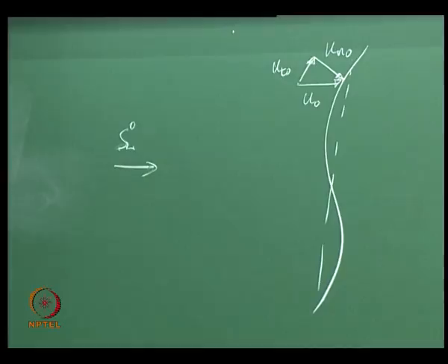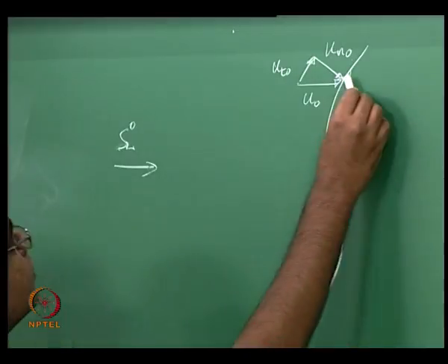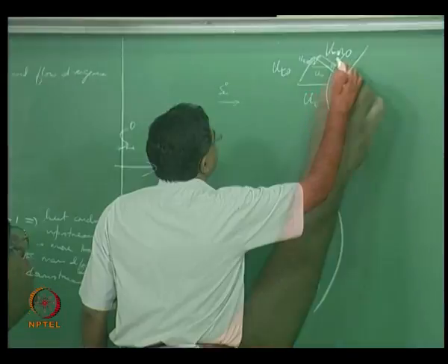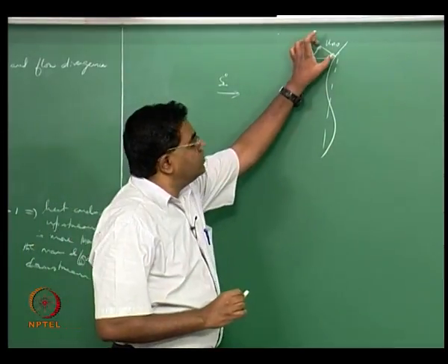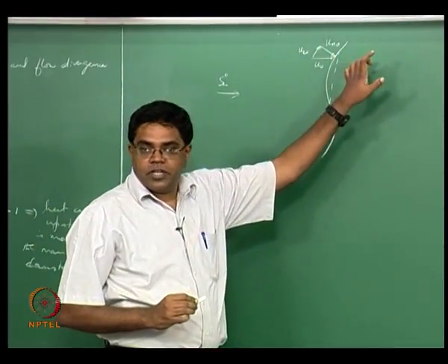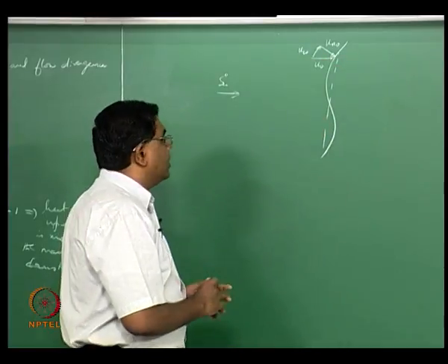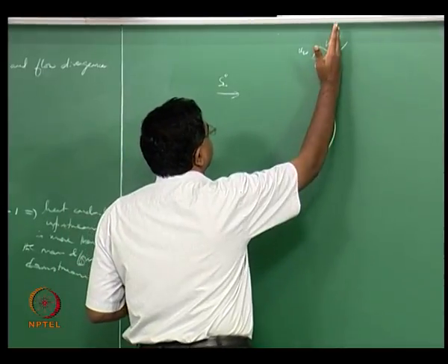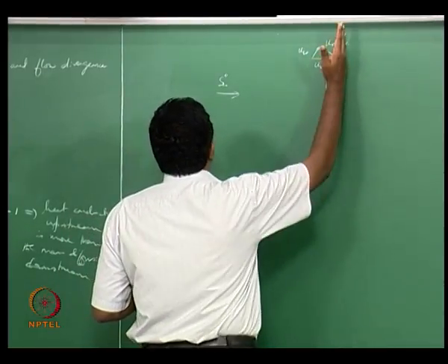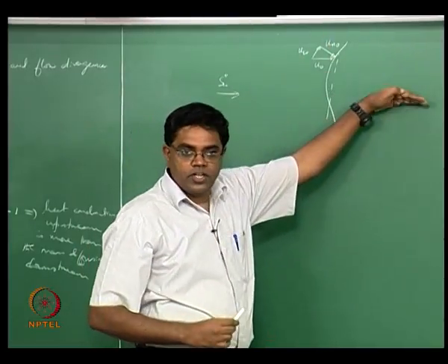What happens is when you have a flow that is going past the flame, it's mainly the normal component that suffers the expansion, because that's how we normally think about a flame. So if you had an unperturbed flame with a flat profile, the normal component of the flow is going to actually expand.